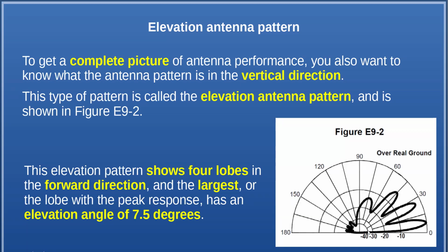You measure that from the largest or most powerful lobe. But because you got these other lobes, you also got power going out in these directions. So even though this one is the best takeoff angle, when we talk about propagation and refractions maybe next week, you're going to get the longest refraction from the lowest takeoff angle. But you don't have as much power in it.